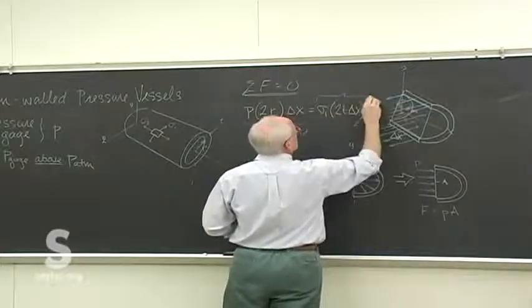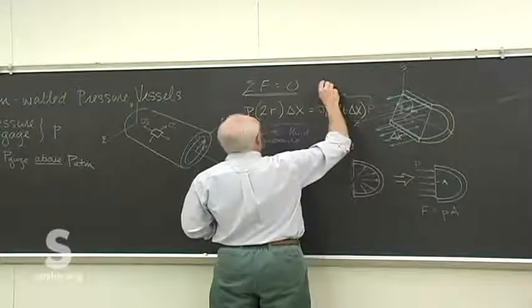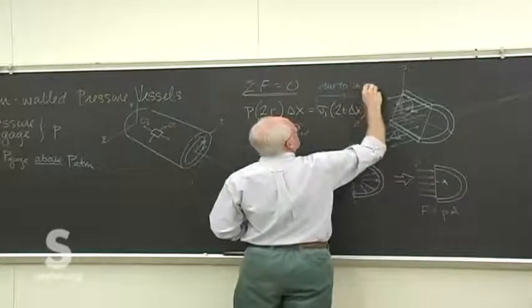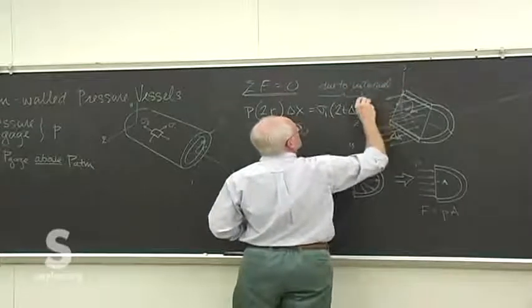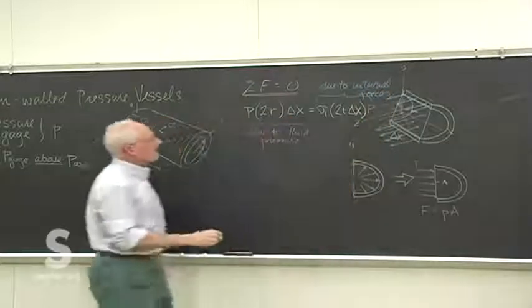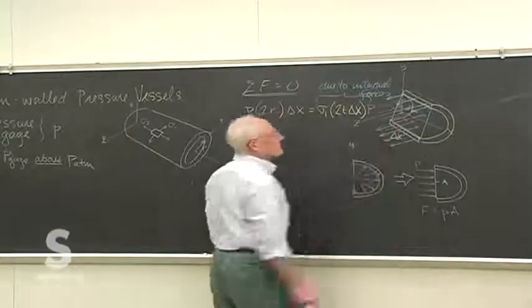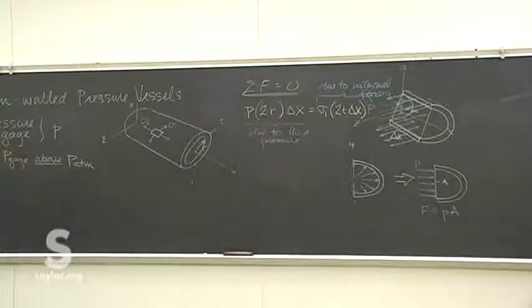And that's due to internal forces in the wall itself. All right, so everybody comfortable with the picture for the most part? We're balancing the fluid pressure forces trying to push this in the minus z direction, and the internal forces in the wall itself as it tries to hang on to the other half of the tank that we've taken out of the drawing.